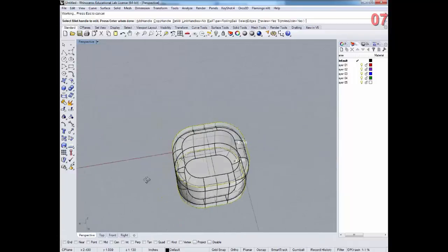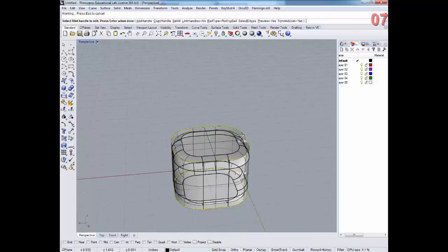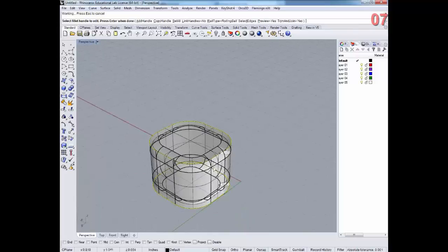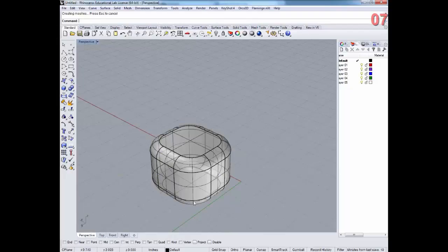Okay, and the reason why I can't go past 0.6 is because it brings up another law of filleting, that whenever you have a vertical edge, remember we did this at 0.1, at 0.6, that was greater than half of what that vertical edge was. So whenever you have one fillet coming into another filleted edge, that filleted edge can never be more than half what that edge is.